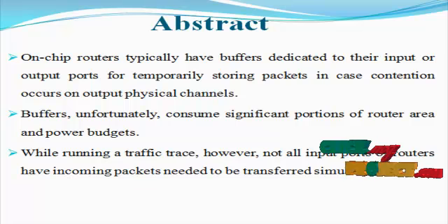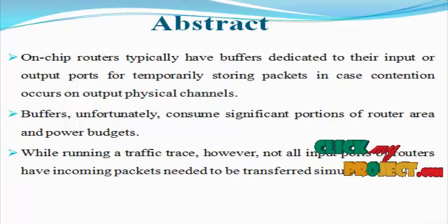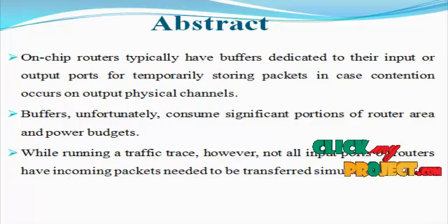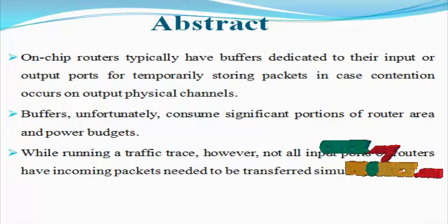motivates us to design a shared queue router architecture that maximizes the buffer utilization by allowing multiple buffer queues to be shared among the input ports. Sharing queues makes more effective use of the buffers, achieving higher throughput when the network load becomes heavy. On the other side, under light traffic load, the router achieves low latency for packet transfer. So we use a star-based topology for our overall routing architecture design, and to reduce the shared buffer processing for the NOC architecture design.